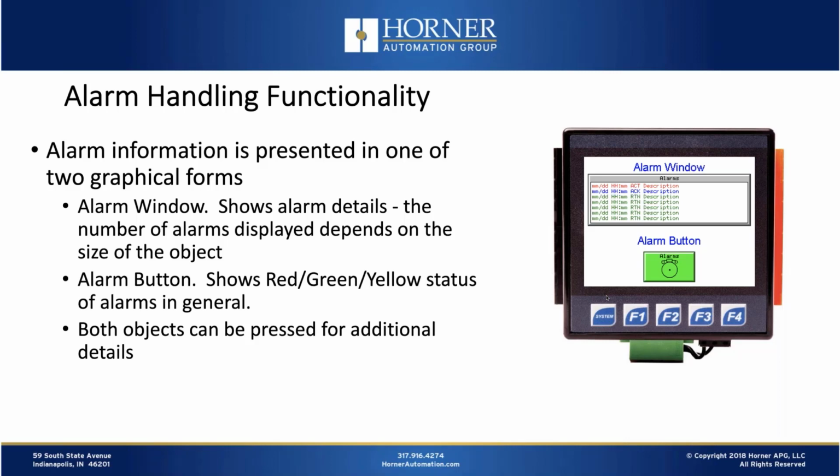Now, in addition to the alarm window, you can also configure an alarm button. The alarm button on its face does not show a lot of detail. At a glance, you can really just see through its color if there are any active alarms or any alarms that have not been acknowledged, etc. However, once you press that alarm button, then again, the alarm object takes full control of the screen and additional details are displayed.